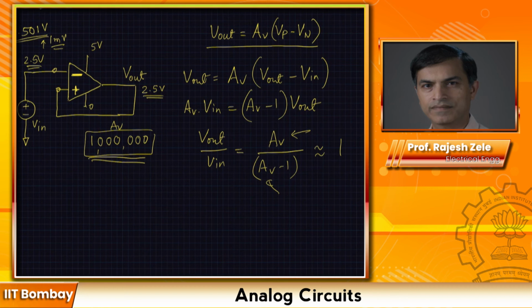If you have answered high, then that's not correct, because we are taking the negative input and raising it positive compared to the other input. Whenever we touch the negative input and take it higher compared to the positive input, the output is supposed to go low. Since the gain is so high, this 2.5 volts will suddenly go to 0 volts, because the gain is so high.